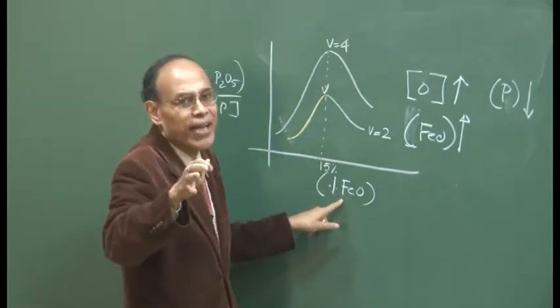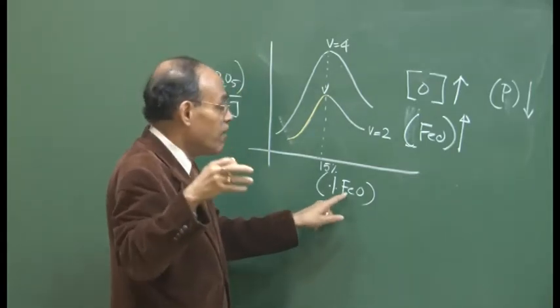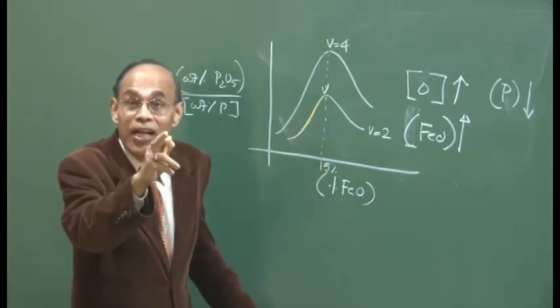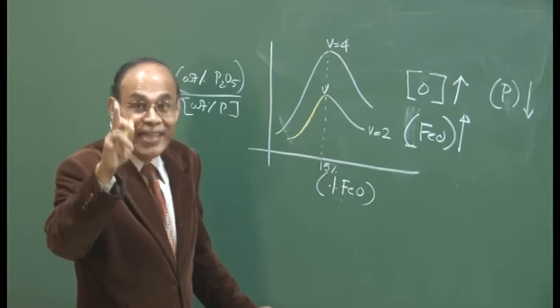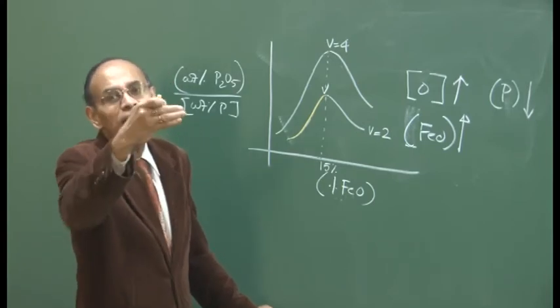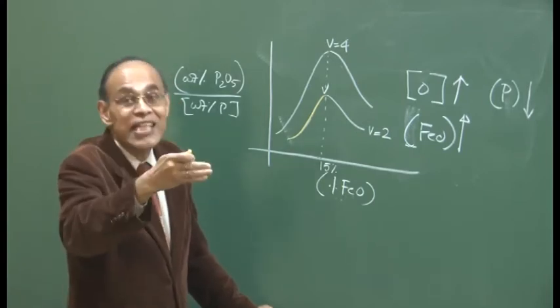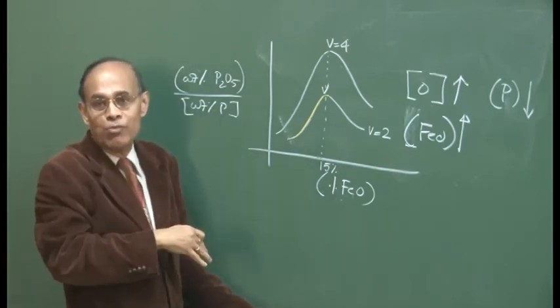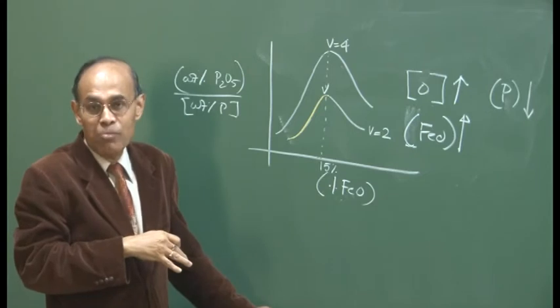I have been telling it repeatedly because this is very important. A high FeO content of the slag coupled with the high temperature generated towards the end of the blow are essentially the reason for rephosphorization of the hot metal, or phosphorus reversion from slag to metal.